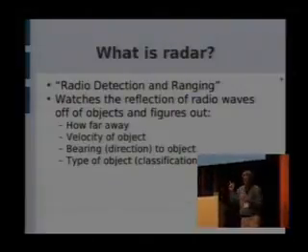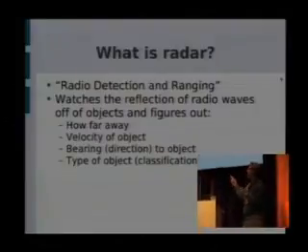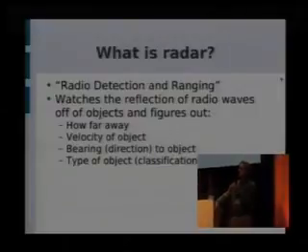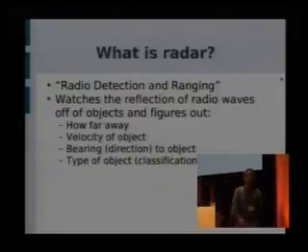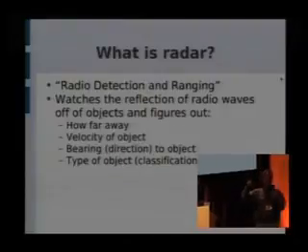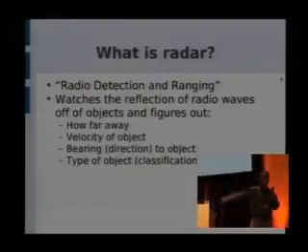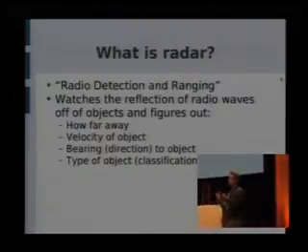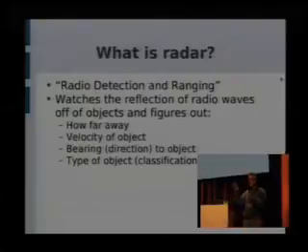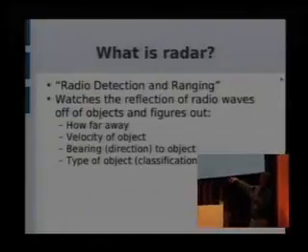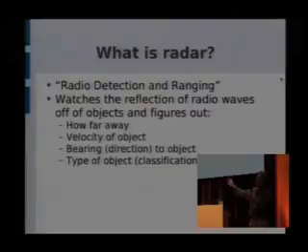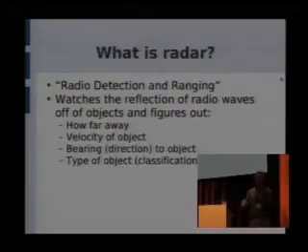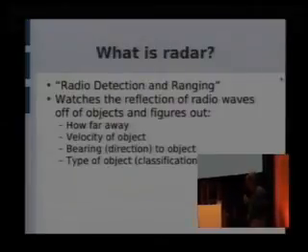There's other cool stuff you can do with radar. When you look at airplanes, for example propeller-driven airplanes, you can actually tell that it has propellers, because the rotating blades show up as sidebands in the radar return signal. Same thing with jet engines, believe it or not. If you have an angle where you can see the turbine spinning, you can say, oh, it must be spinning this fast or it's got this many blades. Helicopters, of course, are the same kind of deal. So there's a bunch of interesting stuff that shows up.